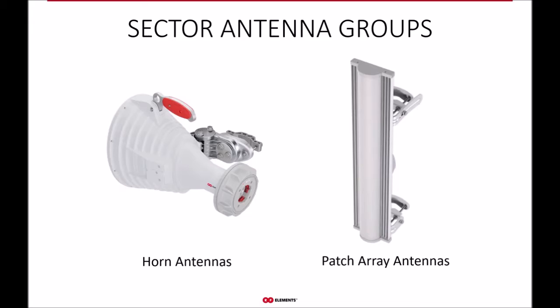To begin with, take the word sector. So why is an antenna called sector? Because its beam width in the azimuth plane is not 360 degrees, meaning that it's not an omni, but only a part of the whole circle is covered. And this part is called sector. That's it. So sector is not an inherent quality of patch array antennas. It has to do with the beam width in the azimuth plane.